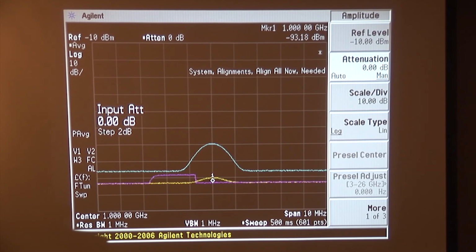Okay, turn it back on. Okay, so I took out 3 dB. That's actually not bad. Instead of jumping up 3 dB, the noise level jumped up 4 dB. But that's okay because that means that the gain plus the noise figure of my amplifier is a little higher in decibels than the noise figure of the spectrum analyzer, but that means the noise figure of my overall system is actually beginning to approach the noise figure of my LNA. So that would be a good place to start then, if you said, okay, now we're ready to start making a measurement, let's turn on that signal like that. Good place to start.